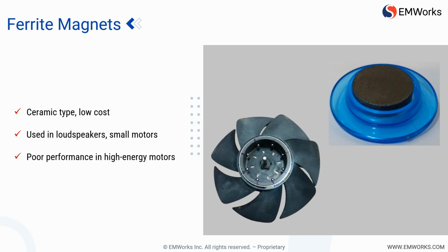Ferrites are cost-effective, chemically stable, and intrinsically corrosion-resistant, making them ideal for large-volume, low-cost applications such as in loudspeakers, refrigerator seals, and small electric motors. However, their major limitation is their relatively low remanence and energy product, typically ranging from 1 to 4 megagauss-oersted.